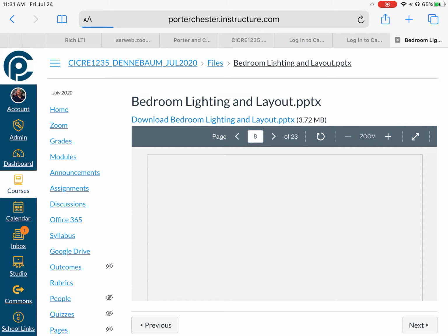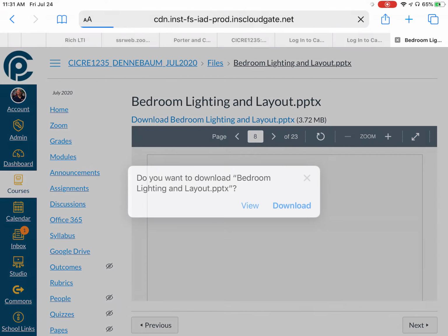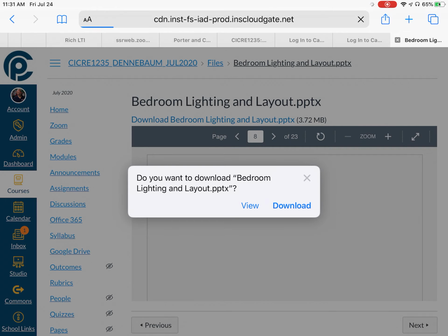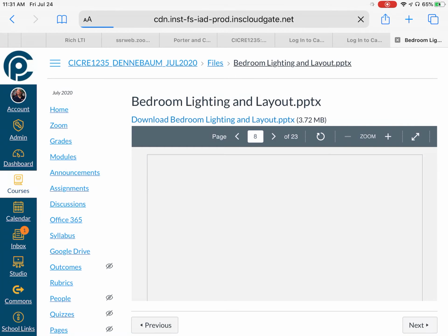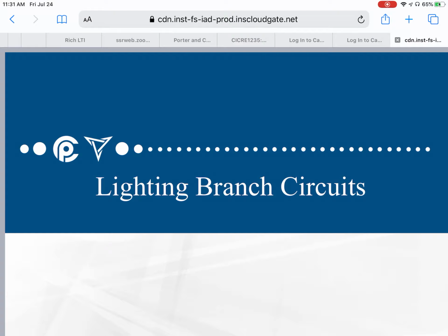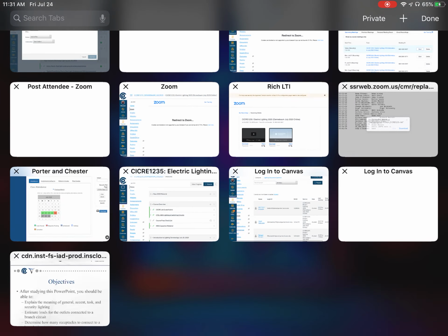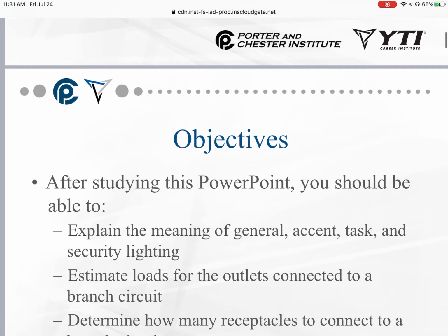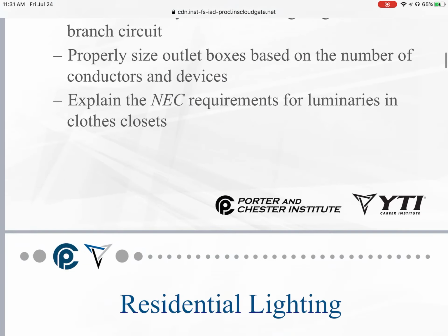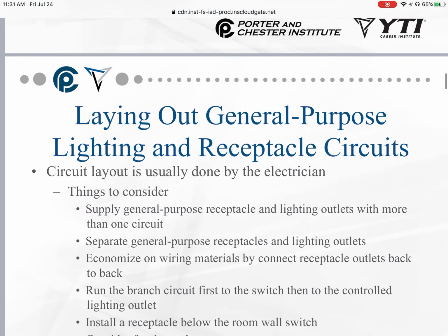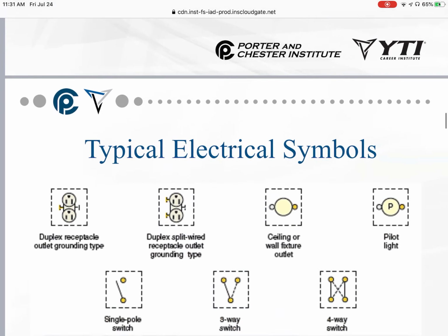So yeah, so we have to have the switches, and also, guys, that neutral has to be at least at one location in a room. So if you have more than one switch location in a room, it's required to be at least one of those locations. It doesn't necessarily have to be at multiple locations. As long as you have a neutral present in that room, in one of the switch locations. That's the other thing as well.